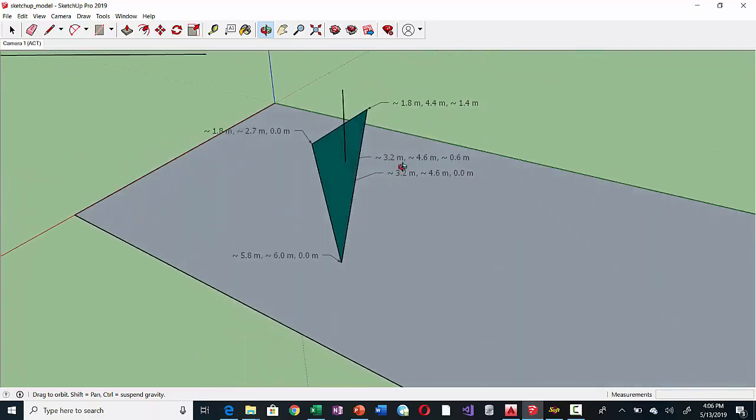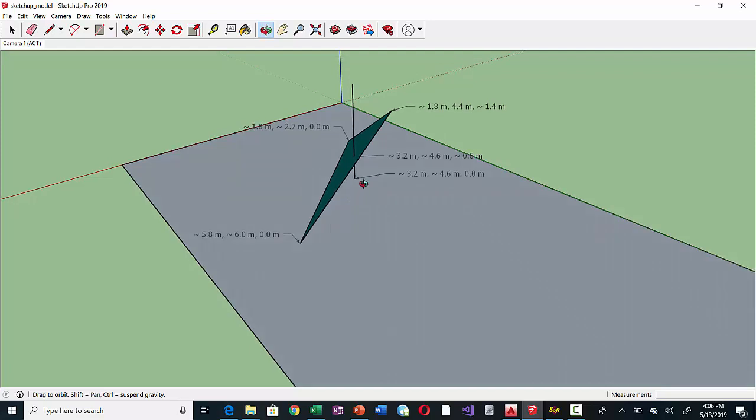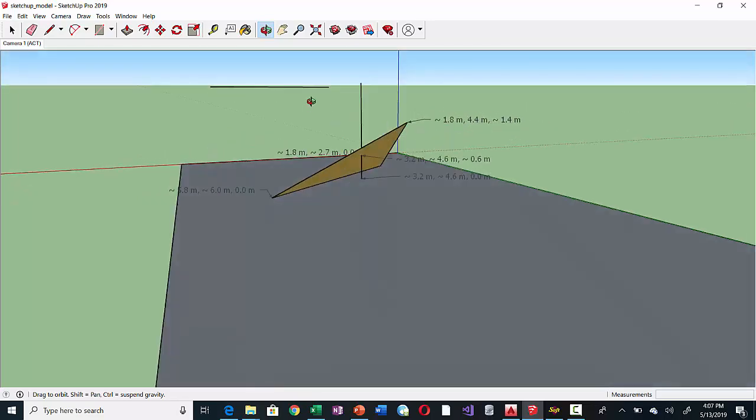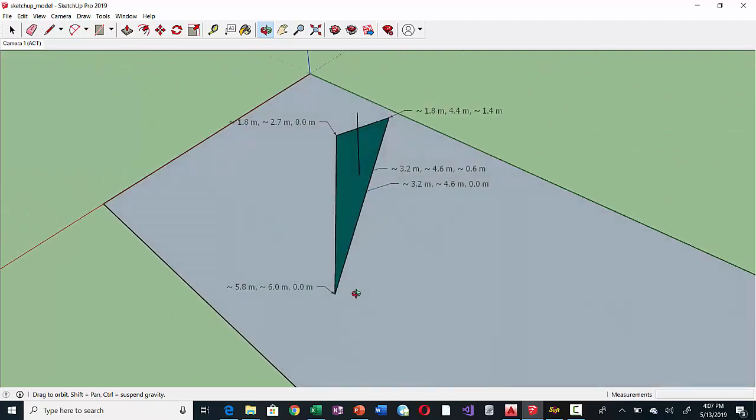So if we are saying the interpolation of this point over these 3 points, then what we are doing is we are extending this perpendicular line from this point to z-axis such that the intersecting point of this line and the plane, this point is the intersecting point, and hence we can find out the value for the elevation, which is 0.6.